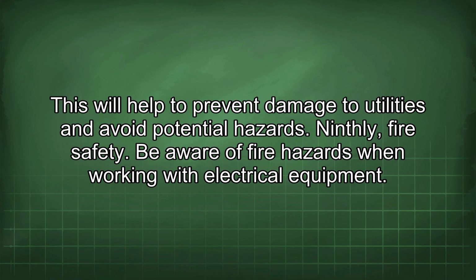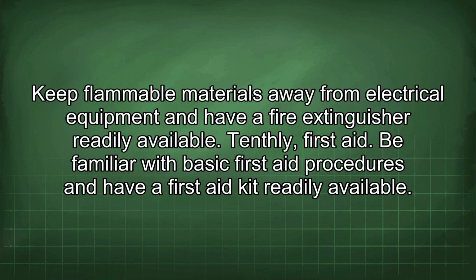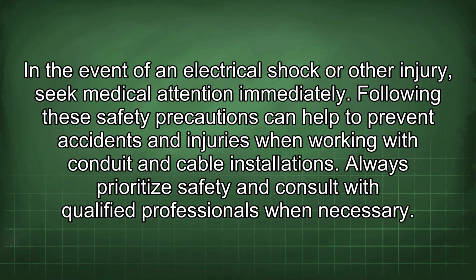Ninthly, fire safety. Be aware of fire hazards when working with electrical equipment. Keep flammable materials away from electrical equipment and have a fire extinguisher readily available. Tenthly, first aid. Be familiar with basic first aid procedures and have a first aid kit readily available. In the event of an electrical shock or other injury, seek medical attention immediately.